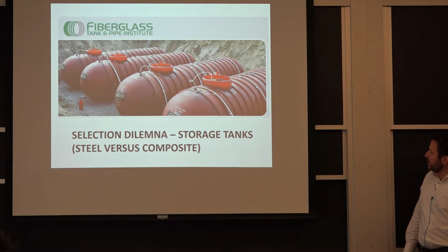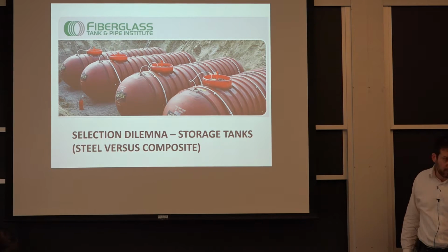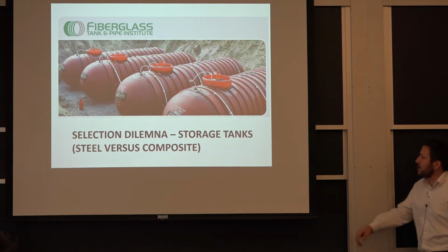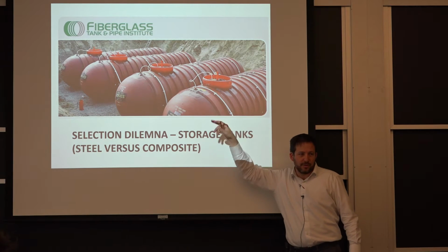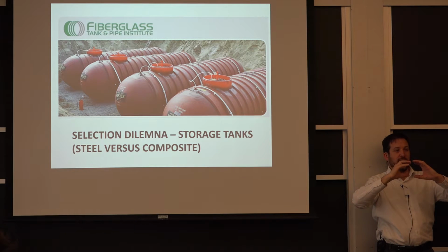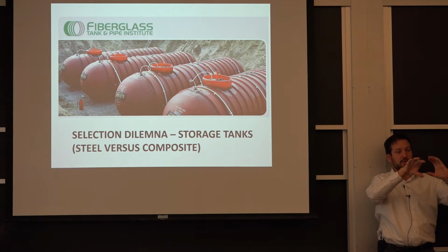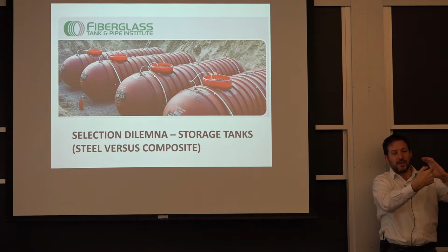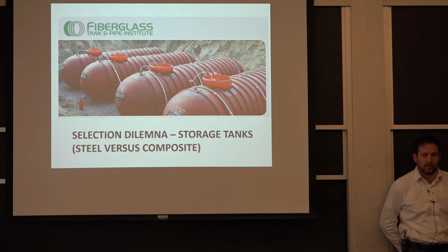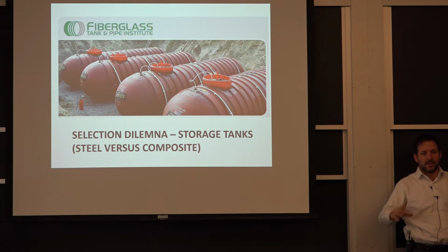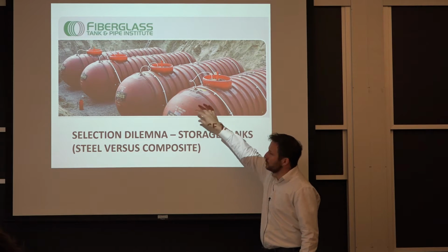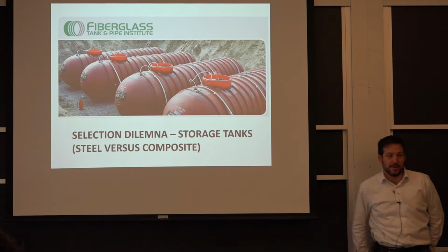I can tell you one issue with turning into an ellipse is the compatibility with the end circle. You can squeeze a cylinder and that's okay, but the cap that goes with it, when you start squeezing it, you're getting tension. You don't have a compatibility of your deformation, and that tends to be a failure location. So one reason for wanting to stay round is to not have breaks between the cylindrical portion and the half sphere at the end.